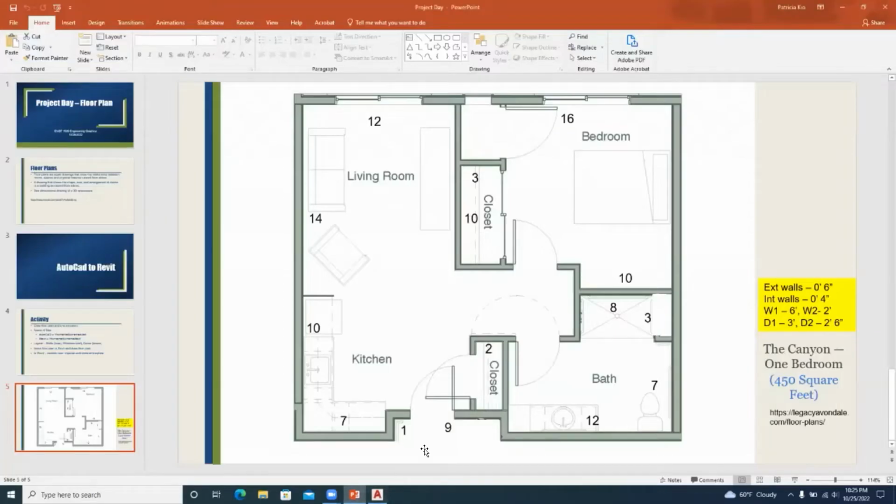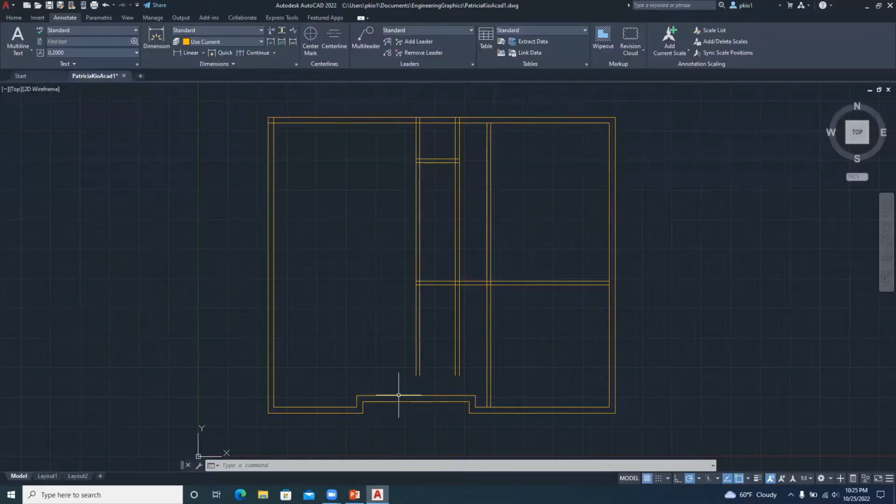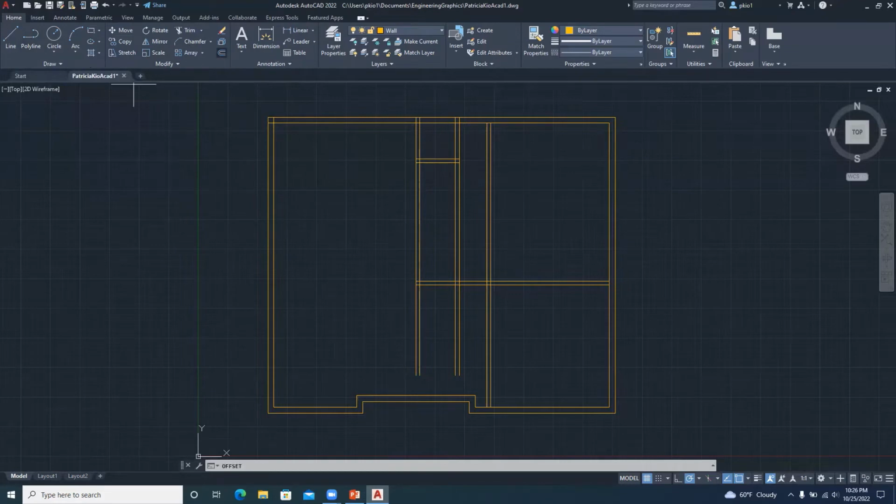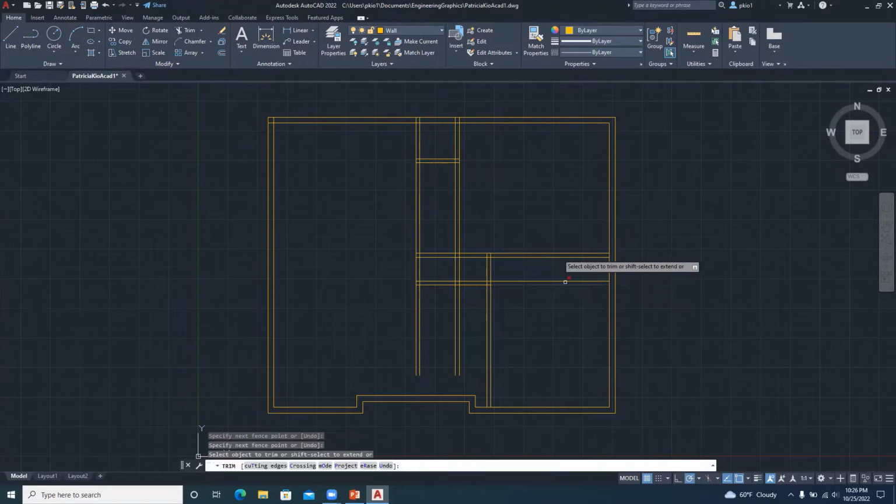Go back to the drawing. Okay, we see that we have a door here. So make this line go up here and then come down by assuming that here will be 2 because that's the standard depth of a closet. So 2. We have this line. And then I'm going to make it by 2 here. So home, offset by 2. And take this way. And then 4/12. And now I'll trim here and here.